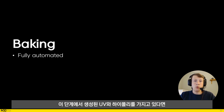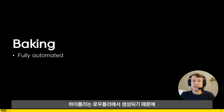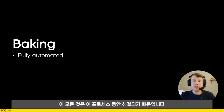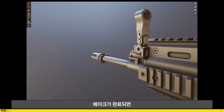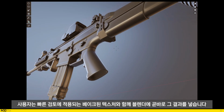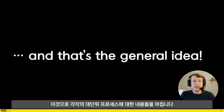At this stage, when we have the UVs and the high poly generated, we want to have the bakes rendered out. Since the high poly is generated from the low poly, we don't have to manually match corresponding low and high poly pieces to each other. That's all taken care of through the process. In order to avoid normal map skewing, a skew mesh is automatically being generated for all low poly parts. And when the bakes have finished, the user gets the results right back into Blender with the baked textures applied for quick reviewing. That's it for each of the larger processes.